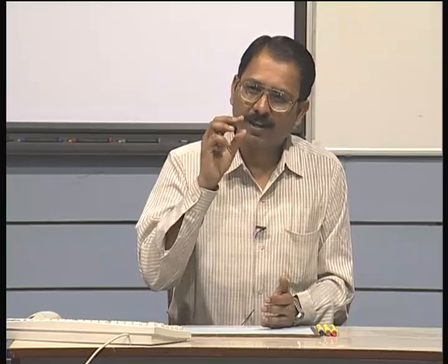Then it may store attributes, like somebody may have made an assembly where you represent parts in different colors, and I would also like to store the color of that particular part, which has nothing to do with geometry or topology, but is an attribute attached to it. Or I would like to store that this particular object is made of a specific material, so material becomes an attribute. So attributes can be stored.